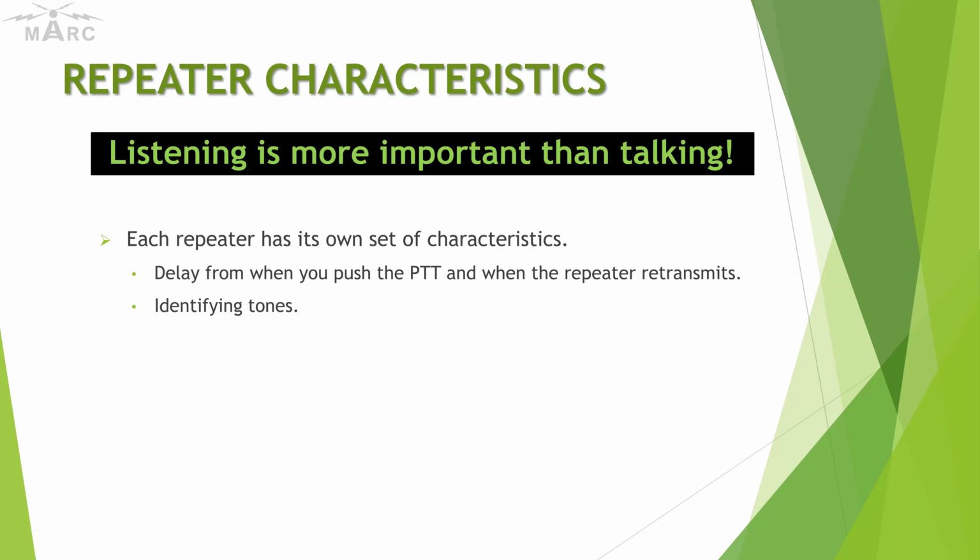Will you find out which repeater uses a transmit PL tone? Yes, I will. Okay, and I'm going to program that in without a tone and see if my radio receives it. It's a simple troubleshooting technique. It's called try it. You can do that with two HTs too. Yeah, exactly. We'll do that afterwards, okay?